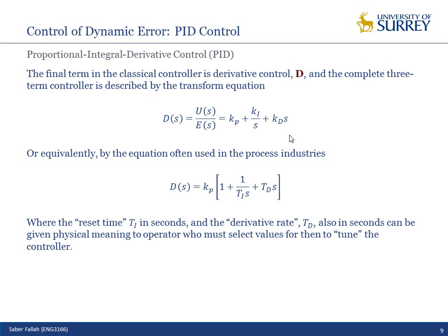No, steady state error. Derivative control in no way can deal with the steady state error. It doesn't affect steady state error at all. Why might it affect the steady state error or type of the system? No, because we have KP plus KDS. If we multiply the transfer function of the plant, KDS is never in the denominator. So it doesn't affect the type of the system. The type is the number of integrators in the denominator. So it doesn't affect the steady state error in any way.